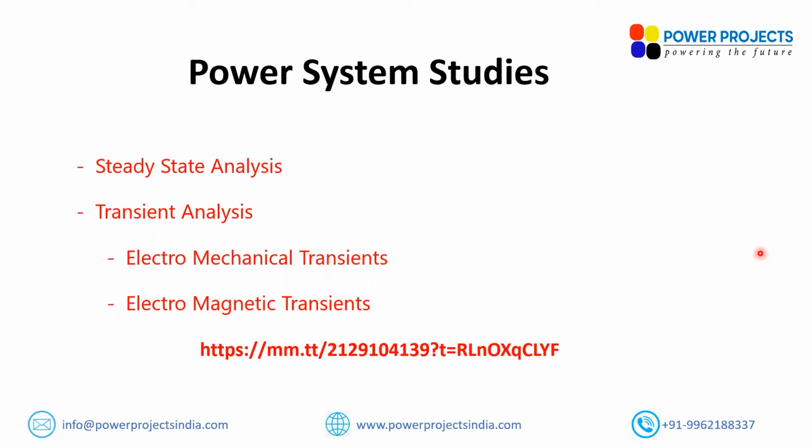Now coming back: is there any electromechanical transient apart from this angular stability? Answer is yes. Voltage stability, LVRT study, HVRT study, frequency ride-through study, whatever we are doing, all comes under electromechanical transients.